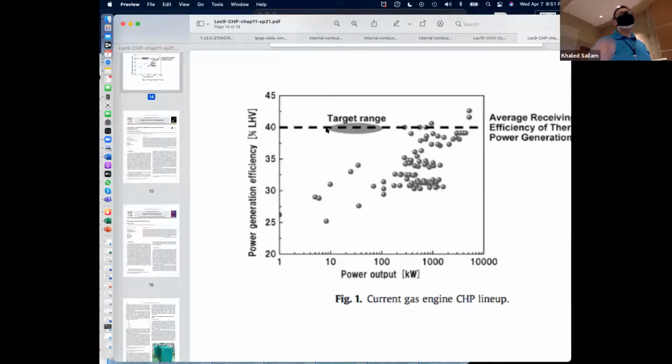Just like a few years ago, California had something called Rule 111 for the emission on any small furnace. Before, small furnaces in our attic or small furnaces for your water heater were a little bit exempt from the emission. And they said, no, any small furnace also needs to be an ultra NOx burner. That made a lot of water heater companies, like Carrier and Rheem, switch to ultra NOx burners, and that made them change their design from the diffusion flame to the premixed flame.